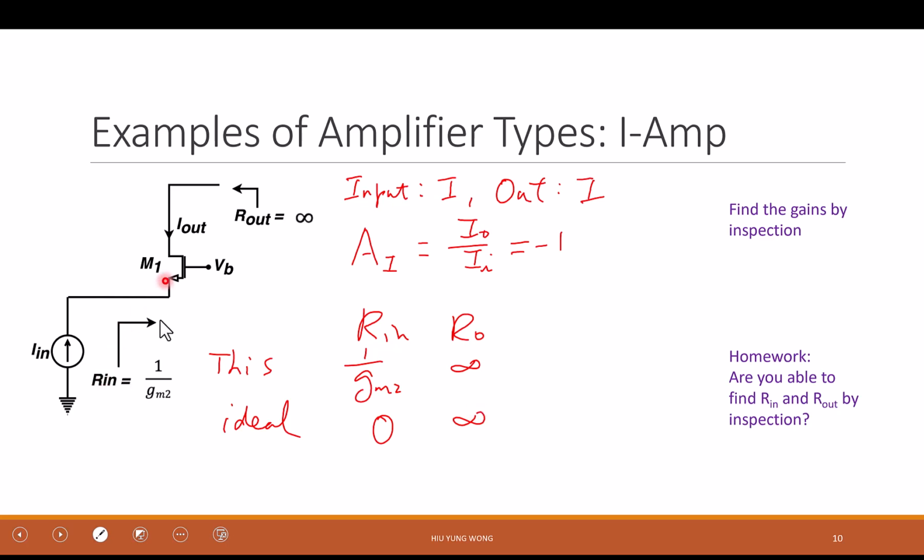So now think about this. Under what situation would I need this circuit? Good. This stage may be a very nice circuit you have designed. It outputs a current. Whether it's an amplifier or just sensing, maybe this is the current that is sensing, I don't know, some leakage, huh? Photodiode, very good. He said maybe a photodiode. We have a reverse bias one, and then we shine light on it, right? And then we have current, and it has a large output impedance.